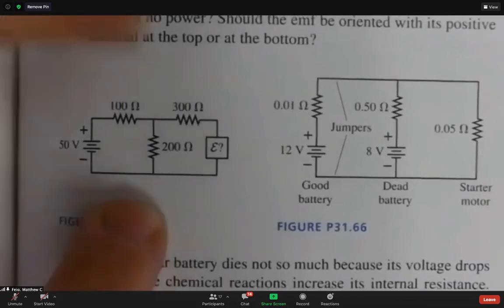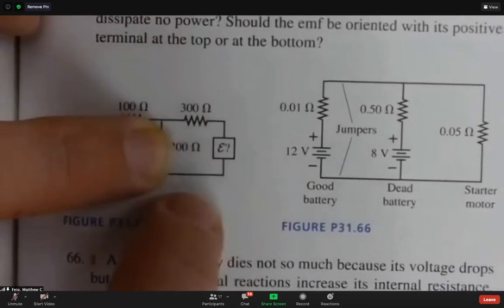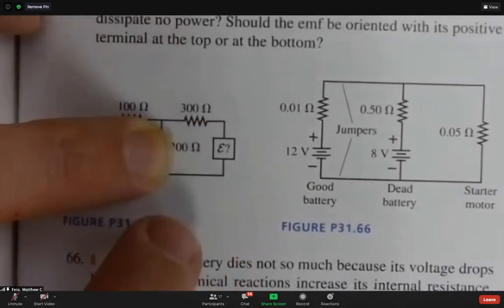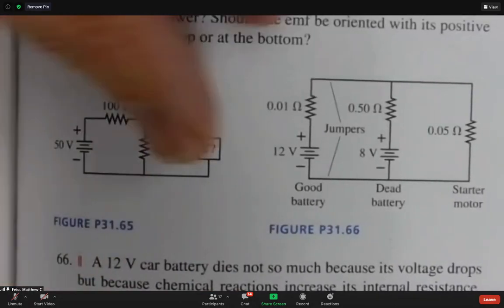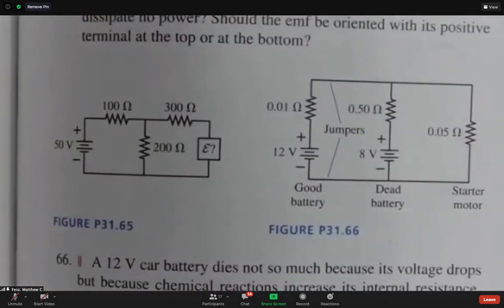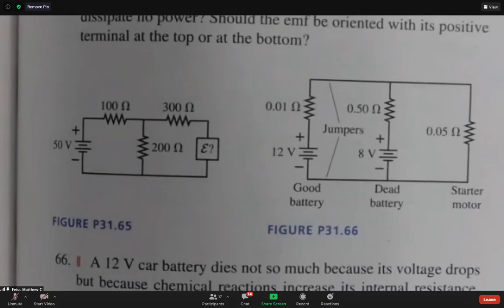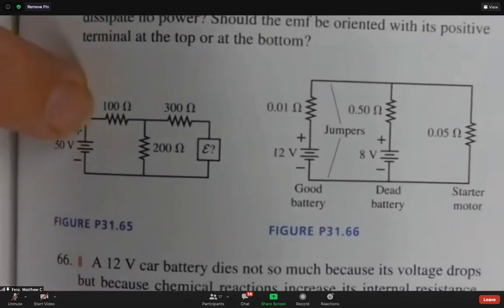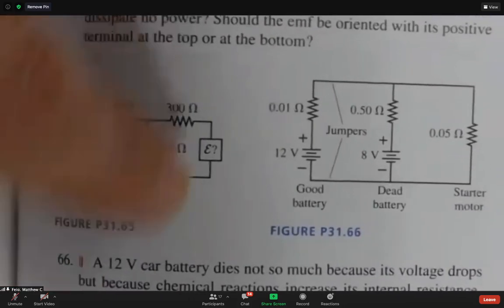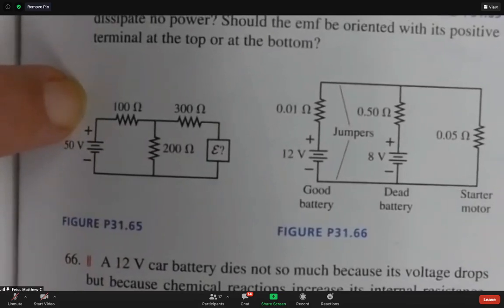What's the voltage from top to bottom here? There's 0 volts. So maybe another way to say it is you can almost do a voltage loop right there, and you could do that over there and get the current. What current will flow around the outer edge of this? I think it's going to be half an amp, and it's going to work out that all the voltage we gain on this battery, we drop across this resistor. So from the bottom middle node, we rise 50 volts, and then we go through half an amp at 100 ohms, and we drop 50 volts.